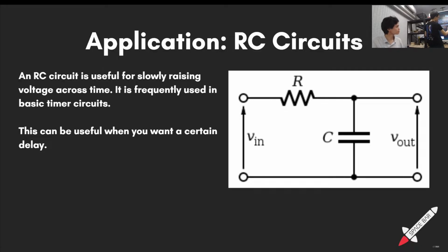After this time constant tau, it reaches 4 volts, which is 2/3 V in. That is how long it takes to reach this point. And usually we will assume after 5 time constants, it is fully charged already.